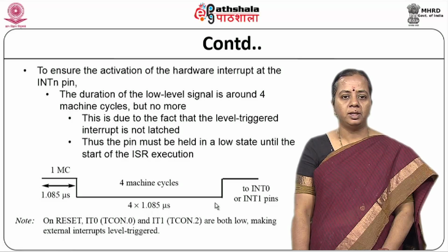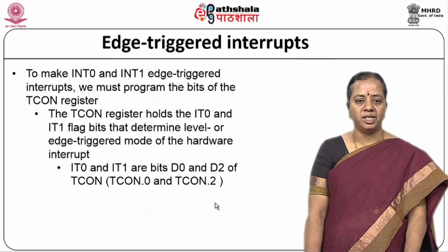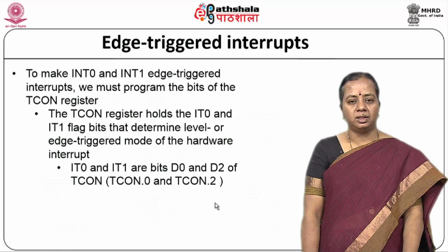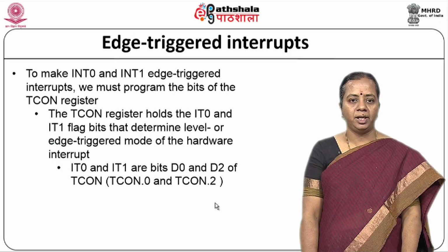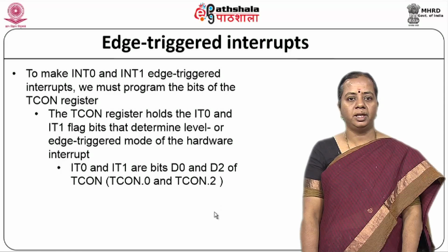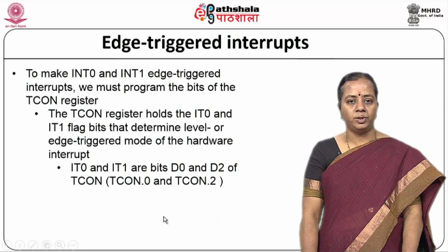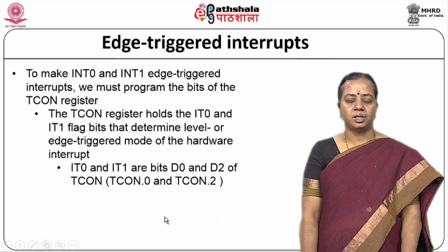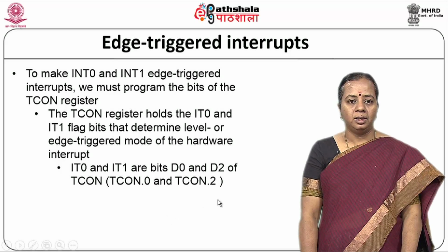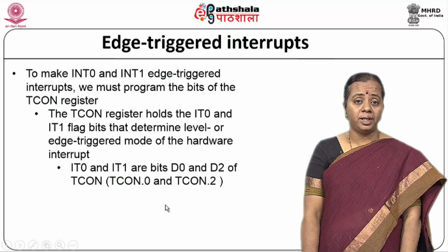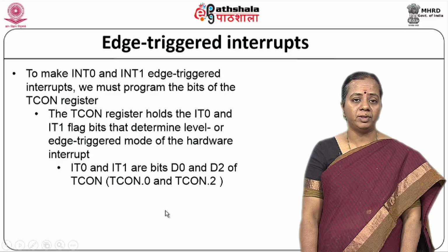External interrupt is invoked. When you are looking at edge triggered, it is only at the transition, just like a spike. If I get a 1 to 0 transition, then I get a trigger, which in turn invokes the external interrupt. Edge triggered is a special kind, and definitely, compared with level triggered, edge triggered is more precise.